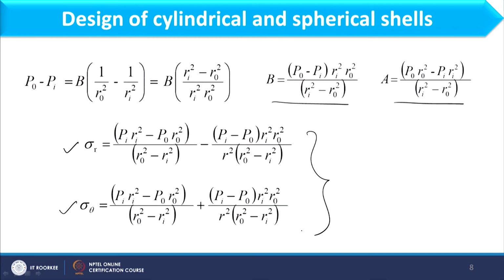Now, if you consider these two equations, both internal as well as external pressures are acting simultaneously. However, when we operate the system, it may be an internal pressure operation or an external pressure operation, but here we will derive the expression for the internal pressure condition. So when I am considering the internal pressure condition, it means the external pressure would be 0.